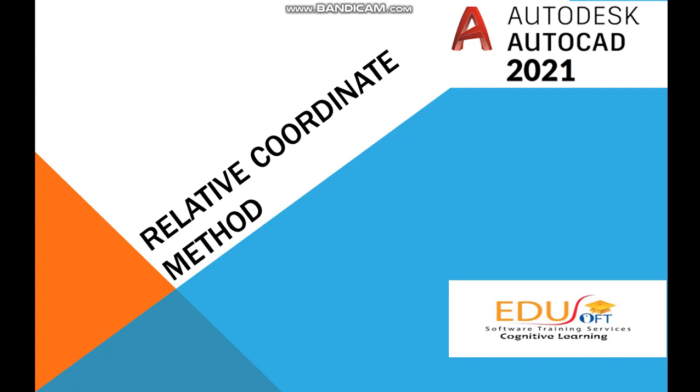But make sure you type @. Before, we have not used any special characters, but in this method we will use a special character, @, before the x direction distance value and y direction distance value. Also, the point at which the crosshair is active will be read as the origin of the shape. That is, when you give @, the software will treat the current active point as the origin.